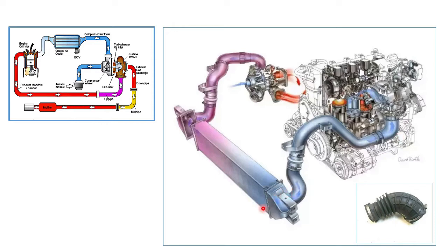If you want to maintain an efficient system, the number of bends should be as minimum as possible, and those bends should not be sharp like this, 90 degrees here, 90 degrees here, 90. There should not be sharp bends like this. The bends should be very smooth at a wider angle, and the number of bends should be minimum possible.